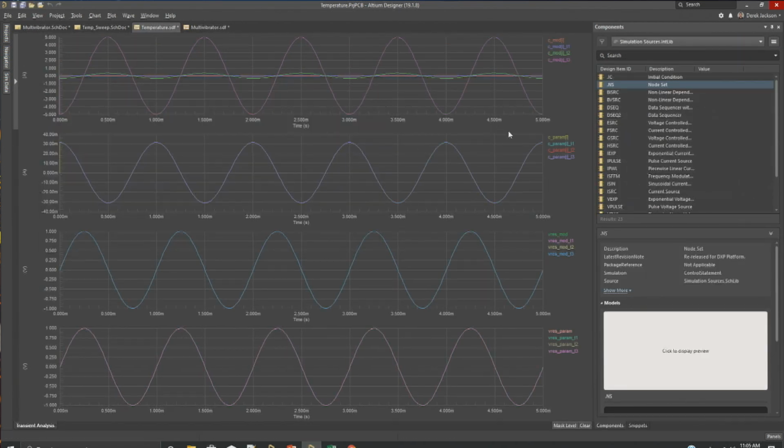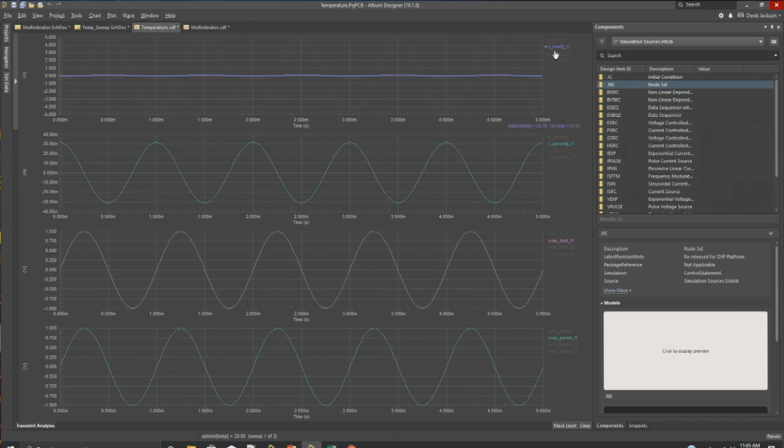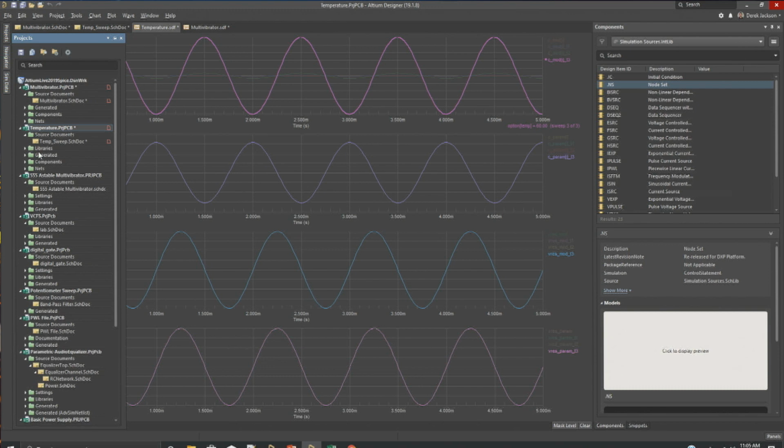and so what it'll do is it'll run. Now for temperature sweep, at the end of each one, it will have a little underscore for the temperature run. So then you can see how that's running. It'll have one without the temperature on there. And then it'll have the rest with the temperature 1, sweep, and 2, so you can see kind of the temperature effects on each of the runs. And same thing for parameter sweep.